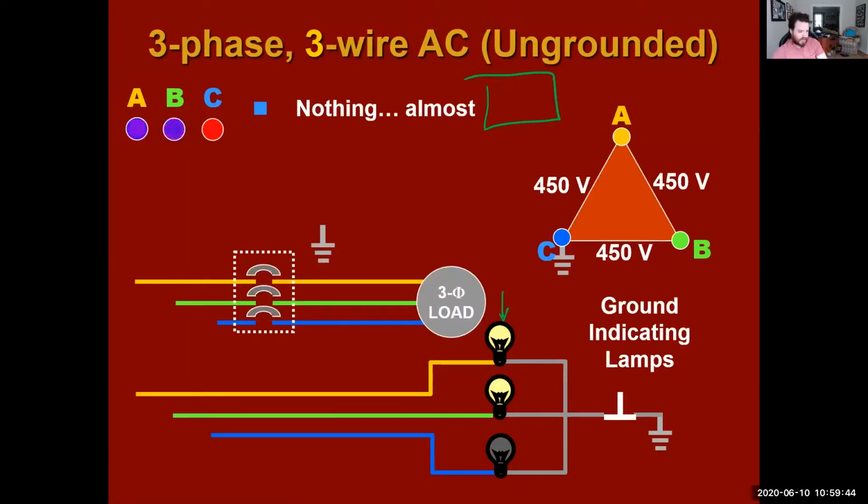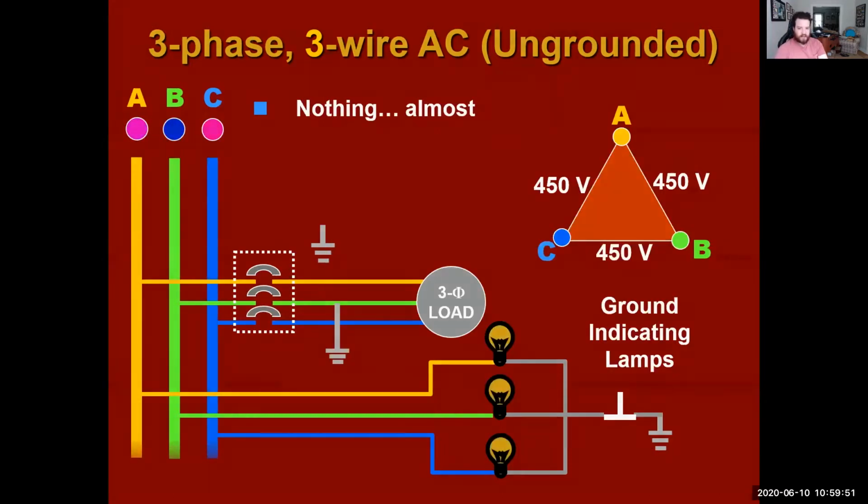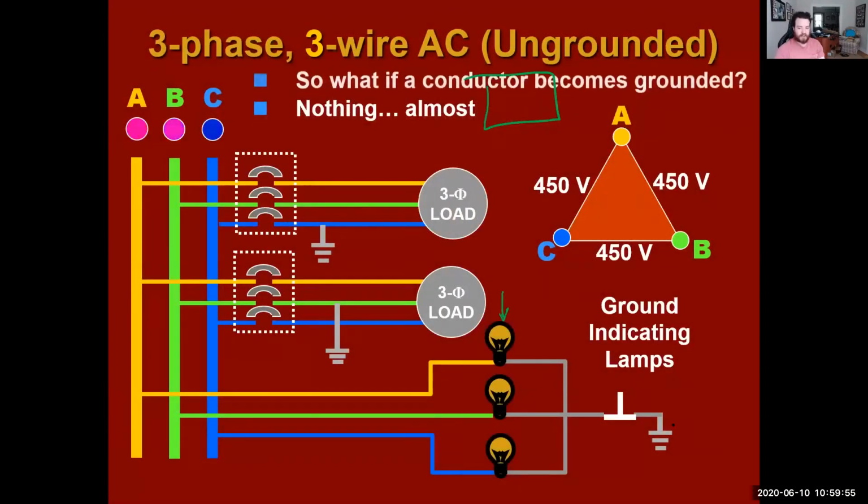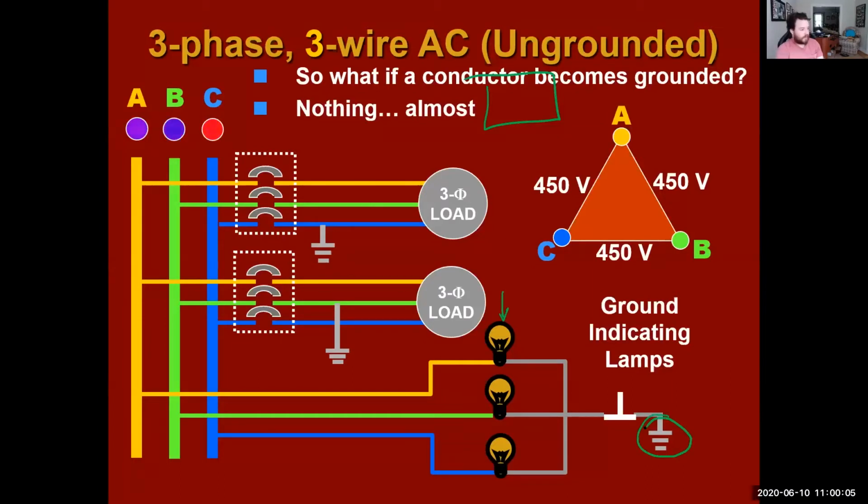And then there's a question in chat. Isn't there supposed to be a connection with metal and circuit for grounding? So when you're grounding, yes, it's going to be contacting a piece of metal of the ship somewhere. Like I said, this ground right here is going to have a physical attachment to the ship. These grounds are not supposed to be there. That can be like a frayed wire somewhere, and then that current's going to be going through the entire ship to this location.